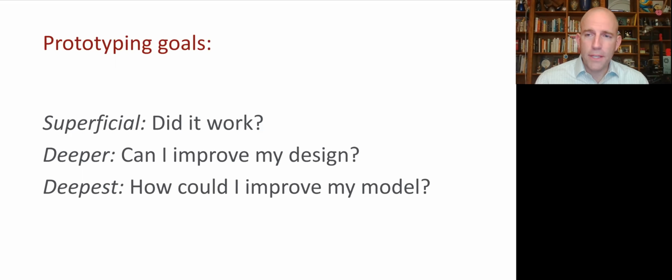For example, there might be simple indications from our tests of how we can improve our design. Maybe the component breaks in a certain location, and we think, well, if I add more material there, it'll be stronger and better, which is good. But the most effective way of using the results of our prototype tests is to map those empirical results onto our simple models of our design. That will give us powerful tools to extrapolate into effective new candidate designs.